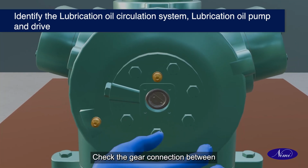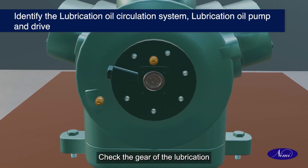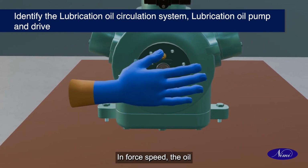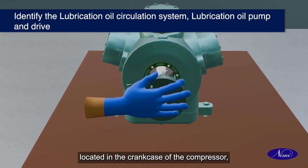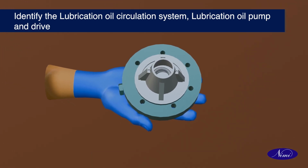Check the gear connection between the crankshaft and the lubrication oil pump. Check the gear of the lubrication oil pump's backlash. Lubrication oil pumps. In force feed the oil is circulated under pressure by an oil pump located in the crankcase of the compressor, usually at the end of the crankshaft.